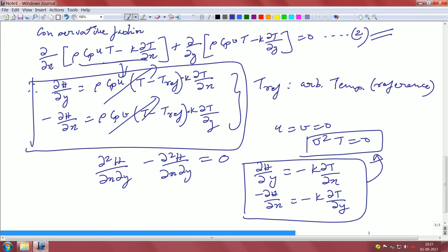So, in this particular case the heat lines become the same as the isotherms, almost the same. The definition is just the same, like your velocity potential and stream function, the same definition once again comes over here. So, this gives us a very composite idea. In the limiting case where there is no flow, it basically becomes the same as your isotherm concept, right. But when there is flow, you actually have additional terms which come into the picture.